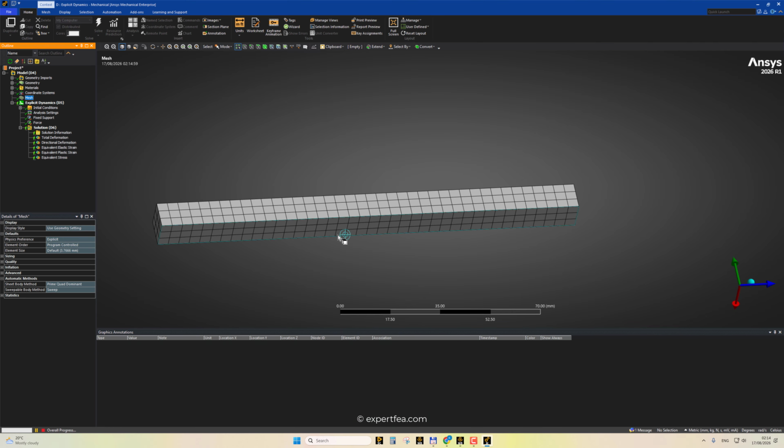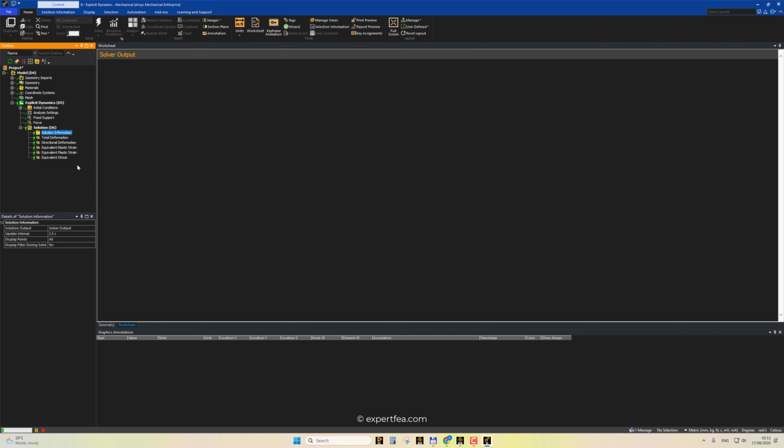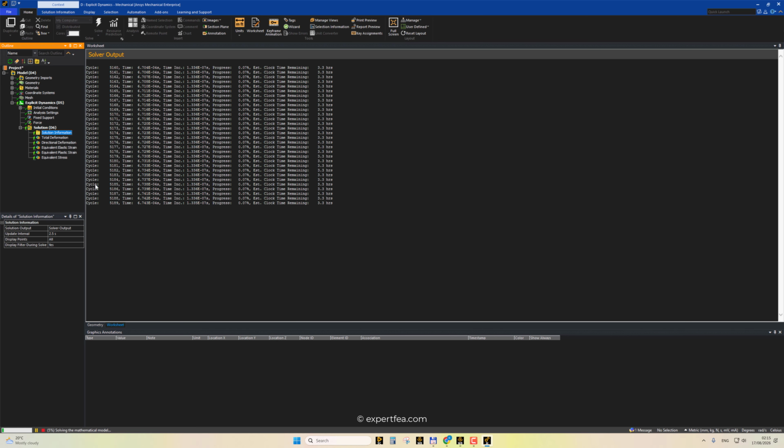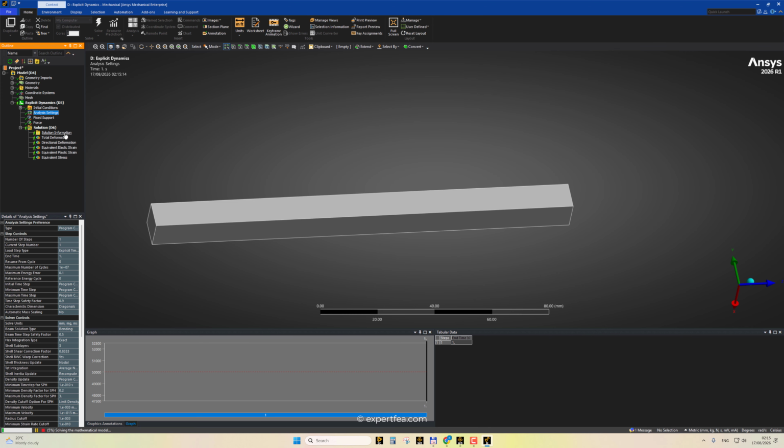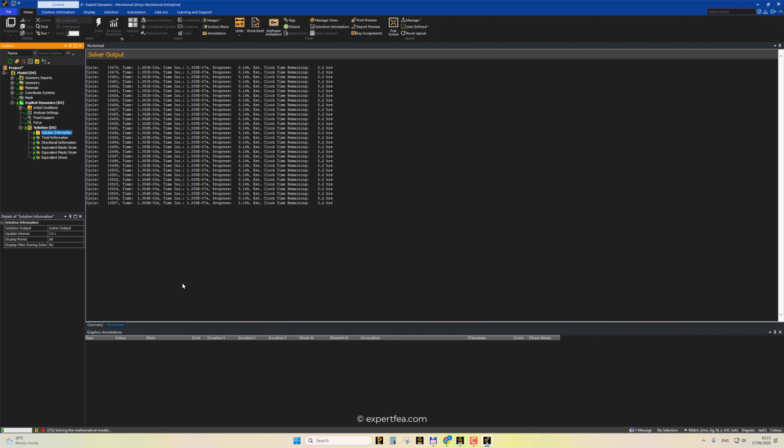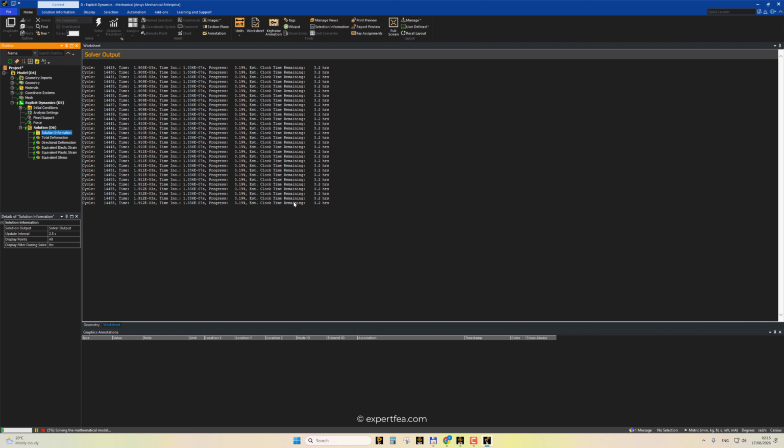How does the mesh look like? It's like this. And the FEA works. Let's see. If we were to use 1 second, the FEA would take 3.2 hours. But I would like to wrap this lesson under 20 minutes. So let's begin cutting and simplifying the simulation while hopefully holding the same request from the simulation. All right, let's stop this.